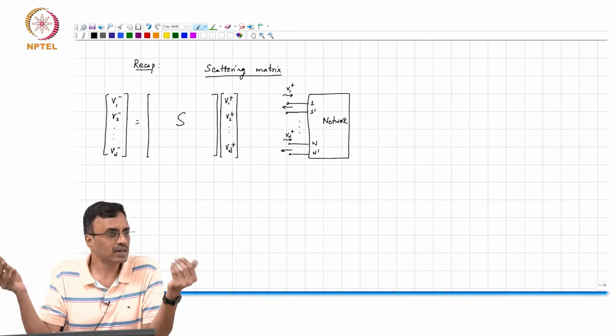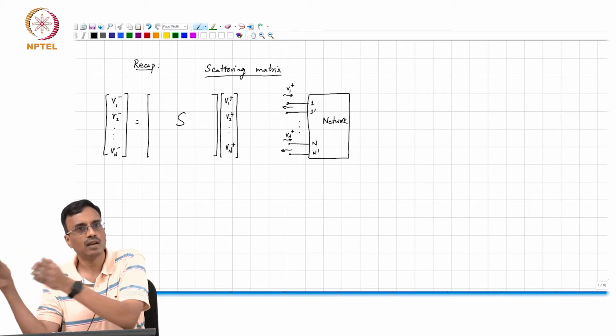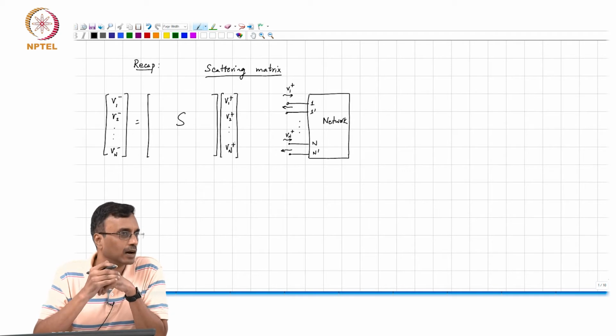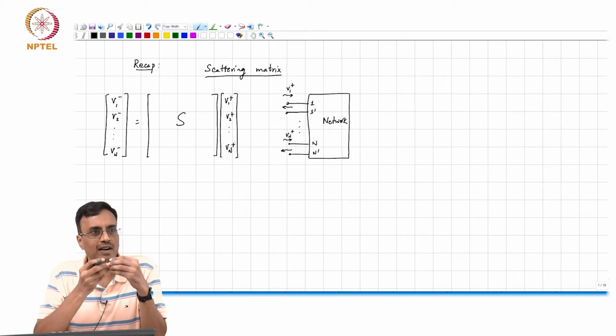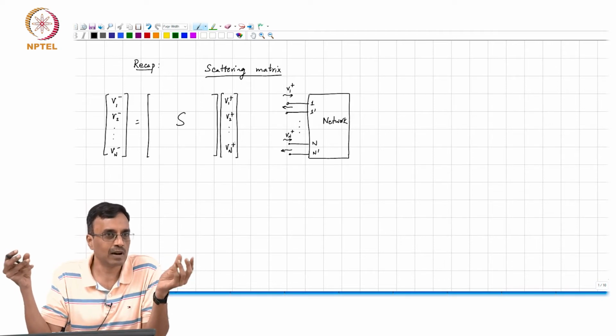And the only way to do it is if you have a transmission line with characteristic impedance Z0, then you terminate it also with Z0, and this way you can have a transmission line which can be in principle arbitrarily long.